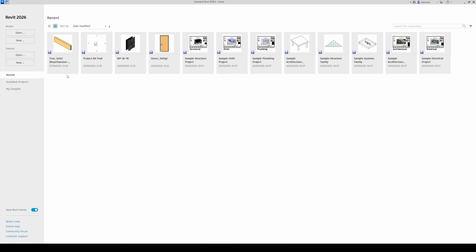So when we want to create a new Revit project, we're going to go to Models and select New. And we'll be encountered with this Construction Template tab, or Template tab in general. These templates are sort of like palettes of families. In this case, families being like some sort of three-dimensional CAD block, like furniture, columns, doors, windows. It's not much to think of at the current stage. Usually I just go with this default construction template. Since I just want to model a simple house, I can just select this template over here.